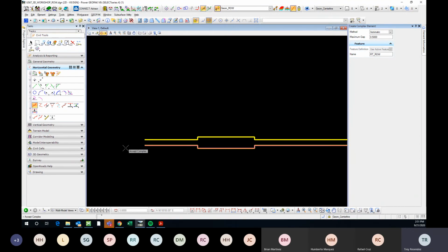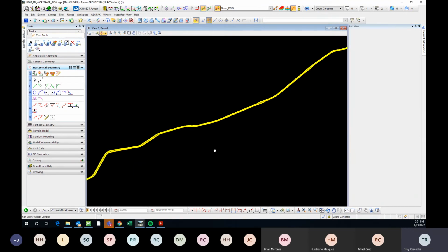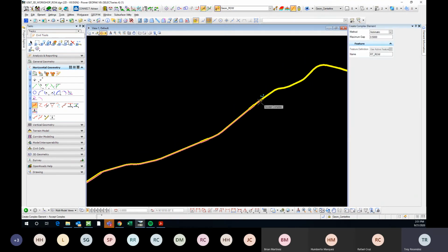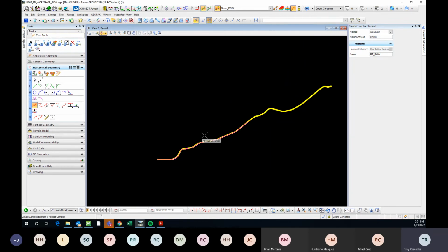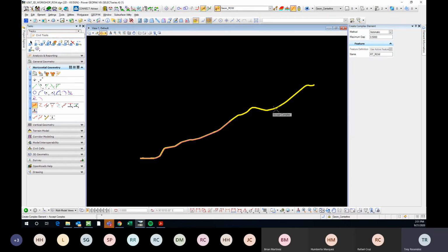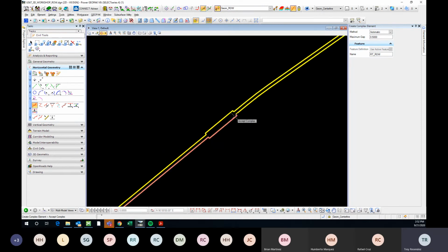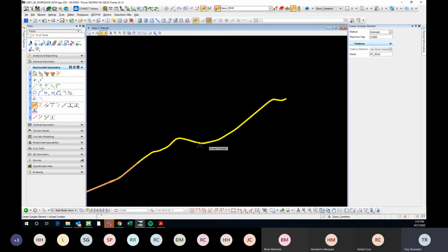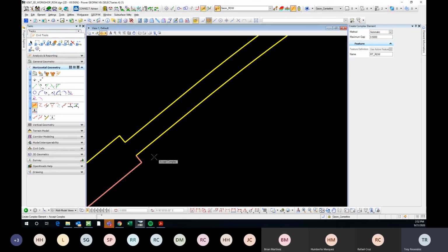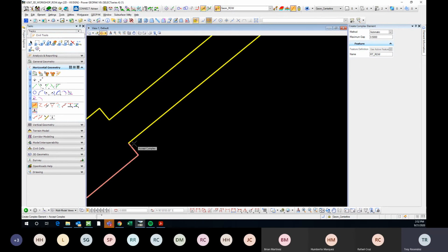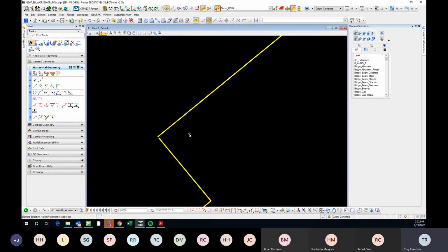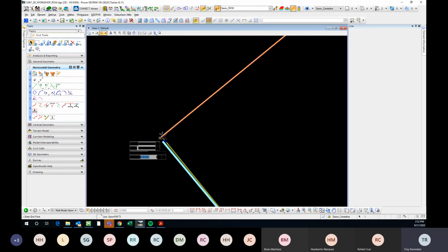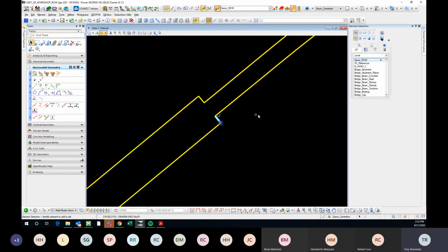You're going to need the right of way, you're going to need the existing terrain, and if you see on here, this is why you should check to see if your geometry connects all the way to the end, because sometimes if it's not connected somewhere, then it won't go all the way. So in this case, I'll just connect these lines, and then I'll do it again.